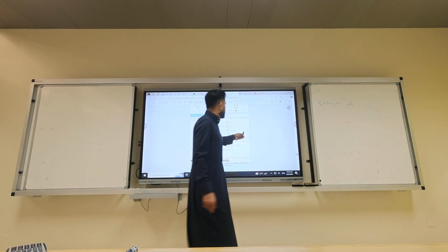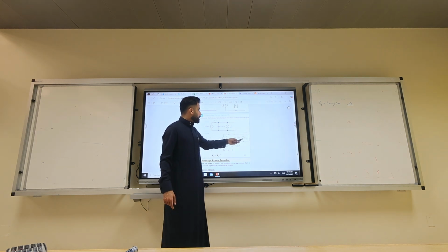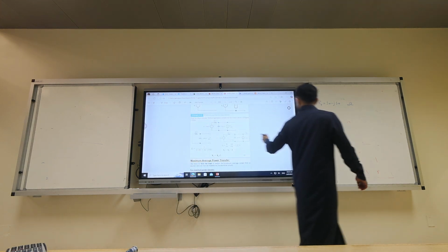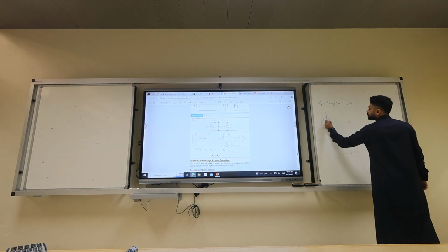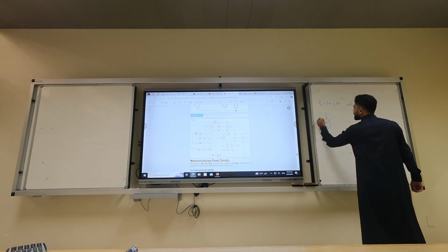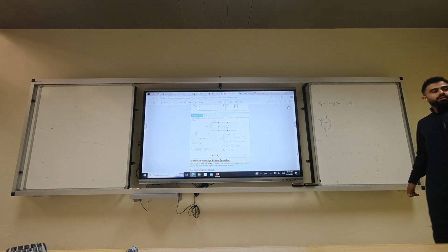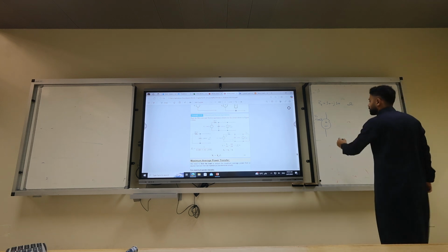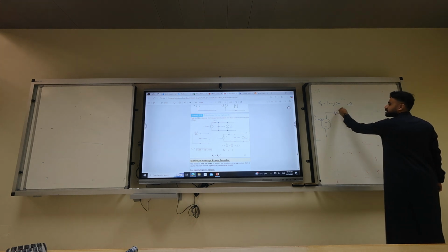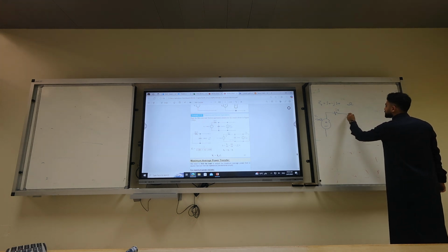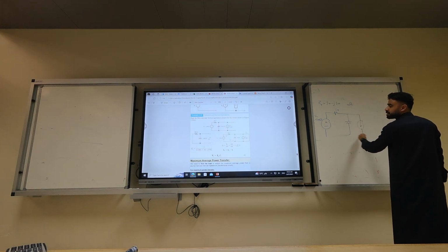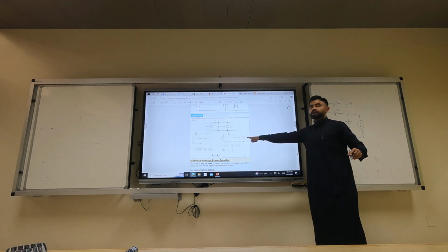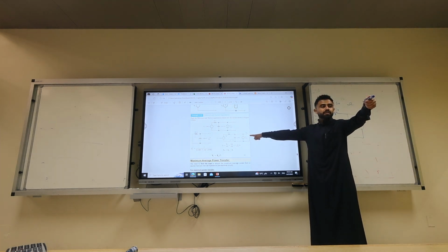So to calculate Norton, we calculate I short circuit. If I make an I short circuit here, that's 100 angle 0. Is 100 max or RMS? Max. And then I short circuit. And then I have a current source. Is the current source 1 angle 90 max? Is 1 max or RMS? Max.